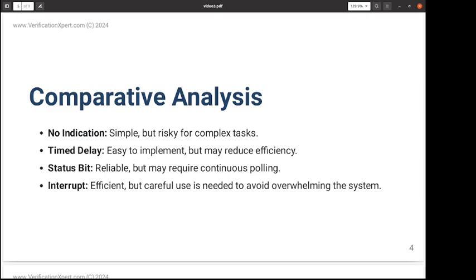Say in some cases you are working on a receiver, receiving some data from the external network. For every packet you receive, if you get an interrupt, it's not a very optimal design, because usually you will get millions of packets per second, right? So in this 1 second, if the hardware is trying to interrupt the firmware a million times, it will again reduce your performance.